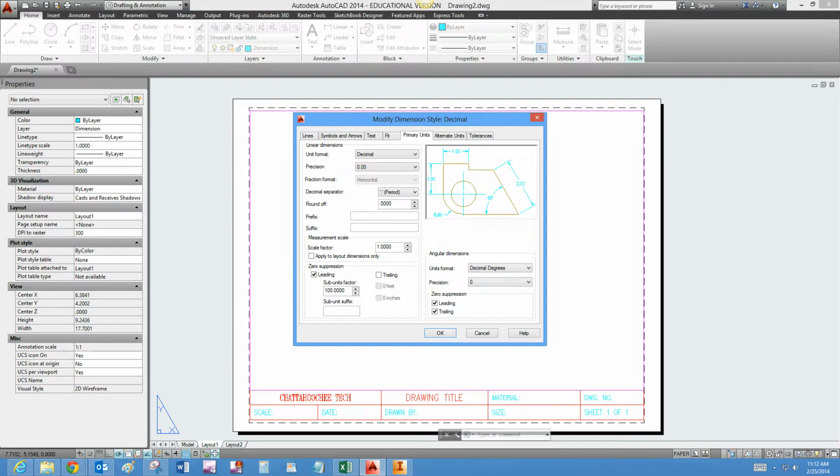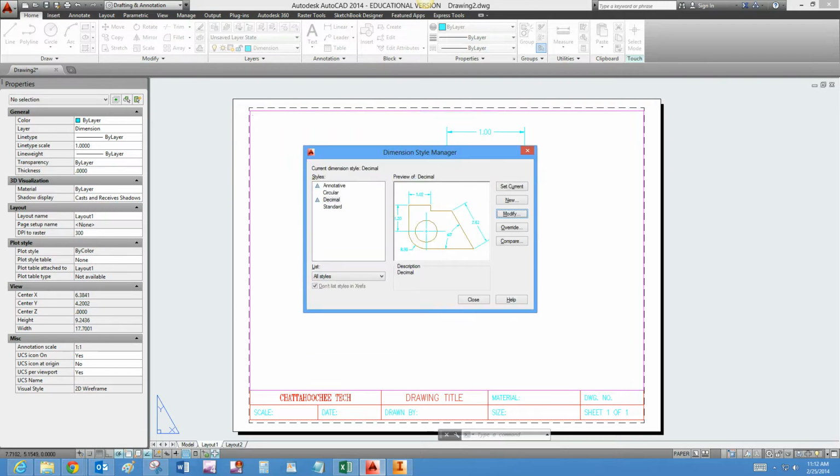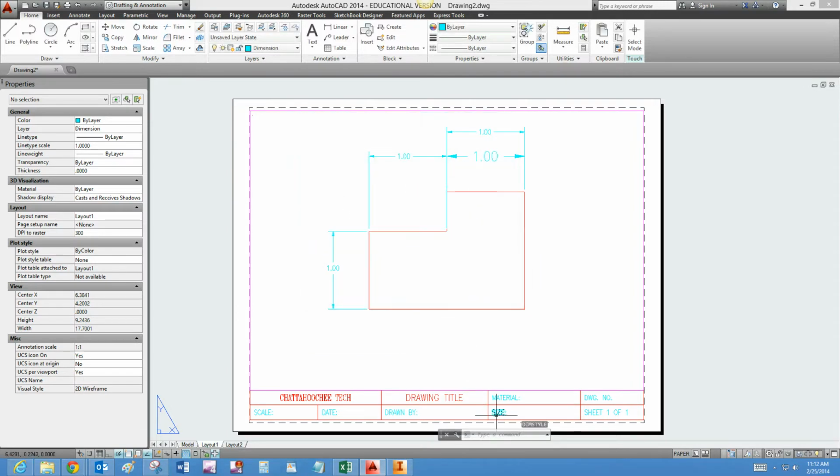In other words, if your dimension was a 1/4 inch in decimal inches, I'm going to just type it here. Your dimension value would be .25. Okay, you wouldn't show it as 0.25 if you're in decimal inch. However, if you need the precision and you're working in a metric drawing and your value is less than 1, you do have the leading 0, so it would be 0.25.